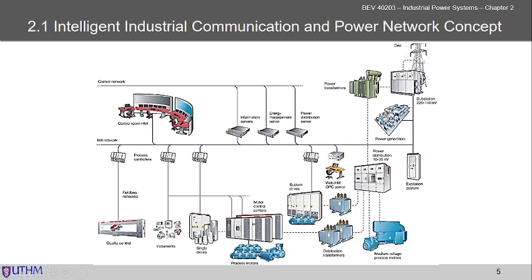So as usual, we lay the cable from the power transformer, the distribution transformer, and they go to the power distribution, which is our switchgear, and go further to the medium voltage, for example from 11 kV to 6.6 kV or 3.3 kV. It depends on our medium voltage needs, and further it will lead to a much lower voltage, for example 415.